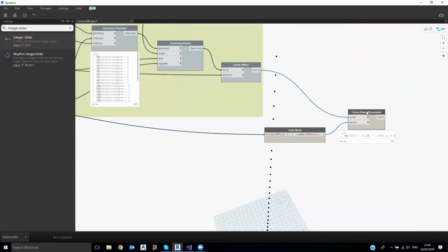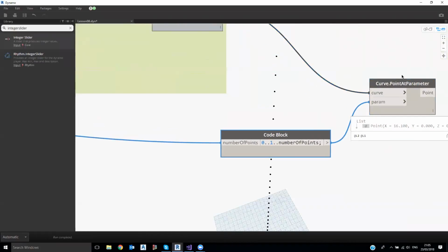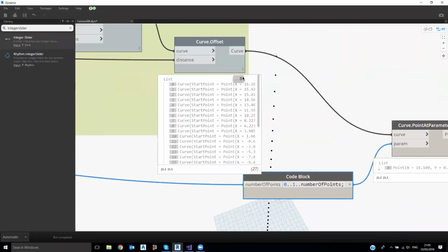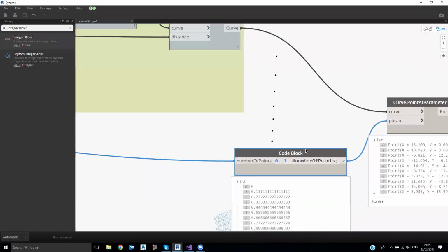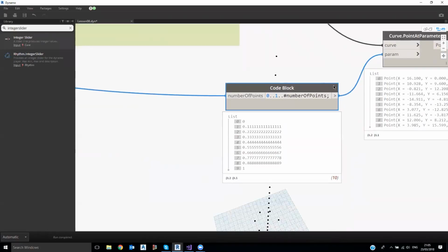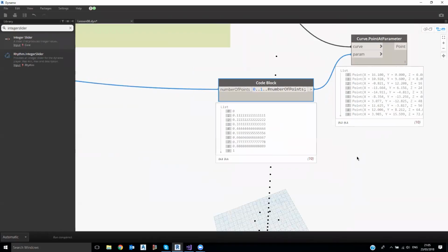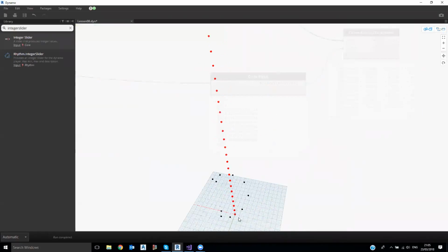And this is the new list. Remember, whenever you have lists of different lengths, because this one is 27, those are 27 curves, and those are actually 10 points. What you need to do to be able to connect both of them is to use a different lacing, because otherwise what you will get is a point on each curve up to 10, but you don't need this.